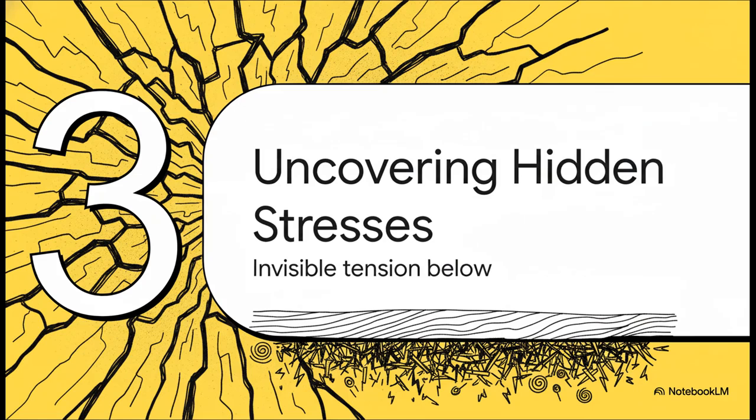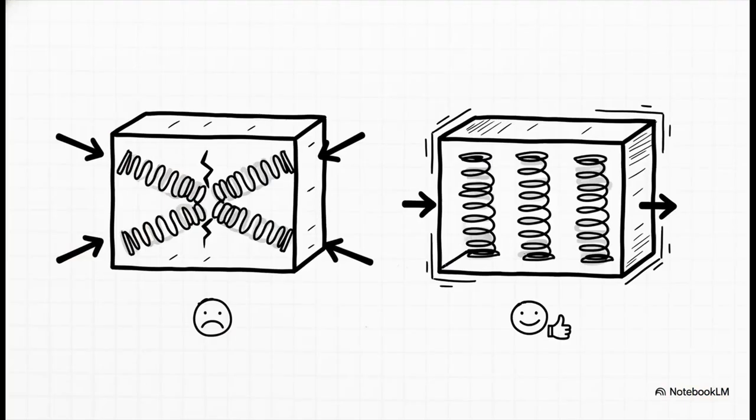But surface texture is only one piece of the puzzle. Now we've got to go deeper, into the invisible world of hidden stresses that are lurking just below that surface. These are called residual stresses. Okay, imagine the manufacturing process locking these tiny, powerful springs deep inside the material. Some of those springs are trying to pull the material apart. That's called tensile stress, and it's bad. Really bad, and helps cracks form. But other springs are trying to push the material together. That's compressive stress, and that's good. It holds the material tight and helps it fight off fatigue.